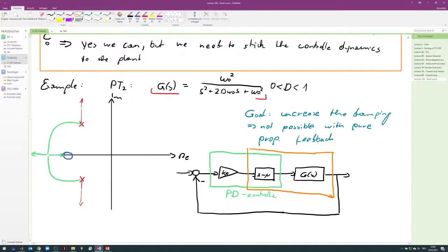zero, you're basically coming to that green line, right? And you again have a line for proportional feedback, because you took that zero and you said as an engineer, oh, I need a zero to increase the damping. So you stick it into your system, and you again get a new curve, right? So you moved that curve from the pure PT2 to this line here, right?